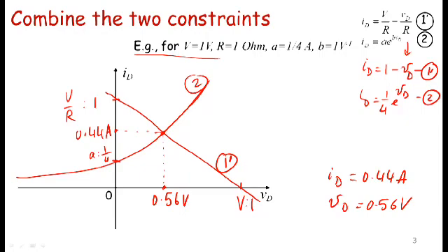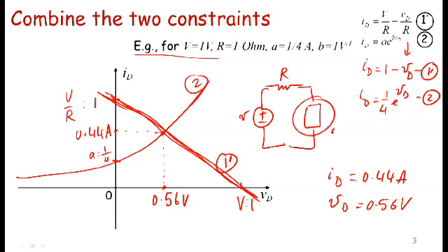Before I jump off to one other thing, let me define something for you. You notice this curve here, this straight line, reflects the Thevenin constraint that I apply on my nonlinear device. And I mentioned earlier, we're going to do this again and again. I think you will see this at least 10 more times in this course, where I take a Thevenin equivalent of some voltage V and some R, and apply that in series across something interesting.